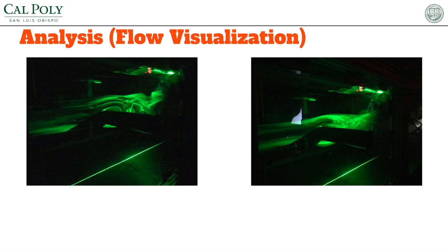In order to better visualize the motion of air around the cylinder, we injected smoke into the test section, which was then illuminated by a 532 nanometer laser. The picture on the left shows a more separated flow and a large disturbed wake. The picture on the right shows the fluid staying attached longer, producing less wake and pressure drag at the same RPM. We took this video during our lab at very low RPMs in order to visually understand how a vortex sheds from a flow interrupting body.